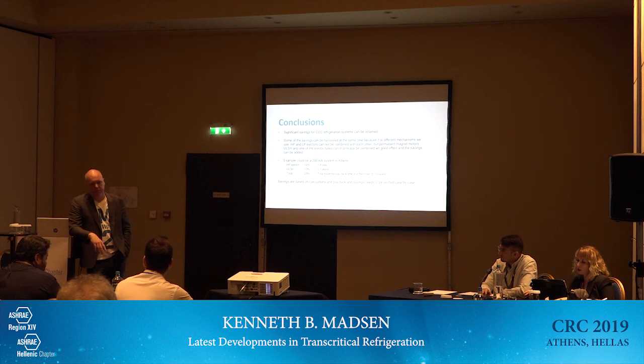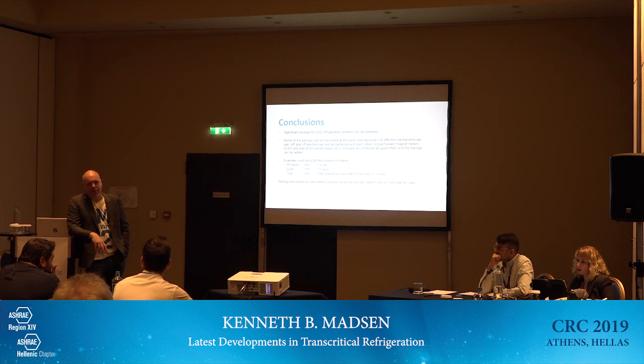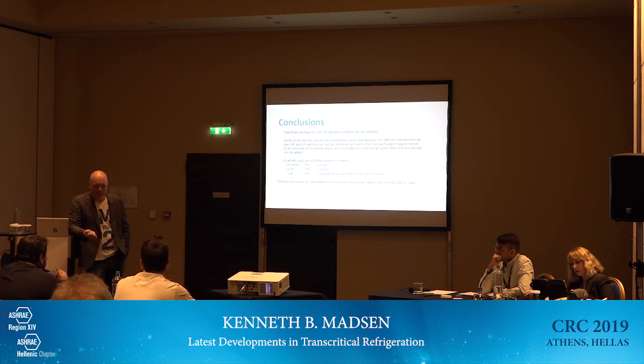And for industrial application, for example, how does it compare with ammonia? Ammonia is a fantastic refrigerant. And to compete one-to-one with ammonia on COP is difficult. It's impossible. But ammonia has some other challenges. We all know that it's toxic and it's also flammable to some extent.